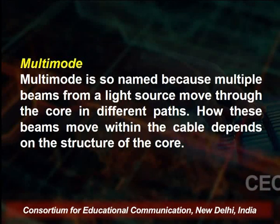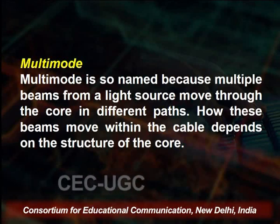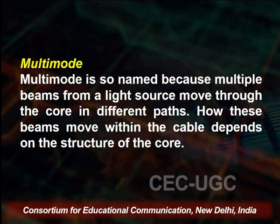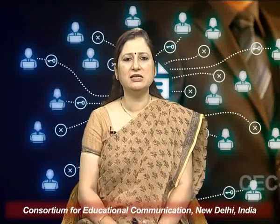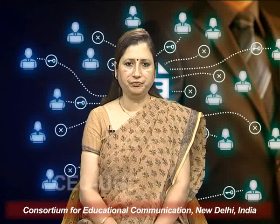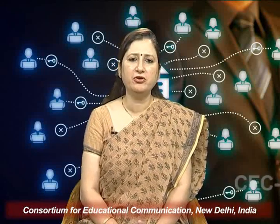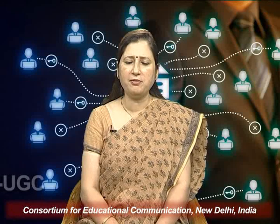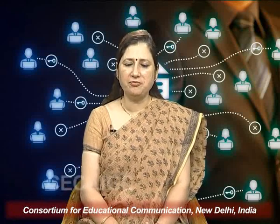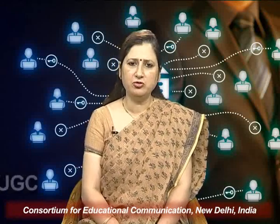Now, how these paths or how these beams will move within the cable will depend on the structure of the core. So, we have understood that there is a core, and outside the core there is a cladding. Now, within the core also, whether the signal will move in a graded format or in a step format, whether it will change its path suddenly, or there will be a smooth transition as the signal moves ahead in the core, is what we are trying to see here.